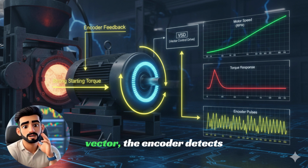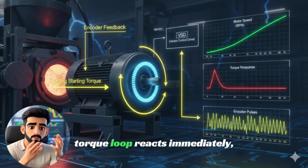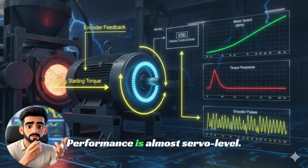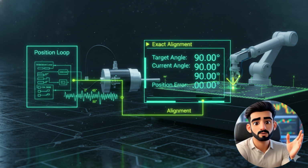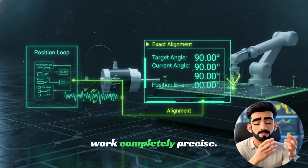In the closed loop vector, the encoder detects load changes instantly. The torque loop reacts immediately and prevents speed dips. Performance is almost servo level. Position control means simply to stop the motor at an exact angle. Closed loop vector plus encoder, these make the work completely precise.